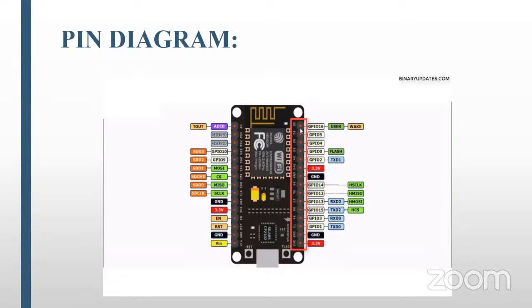Via SPI communication only, we externally read the data from the MCP3008 IC. If you are using only one analog sensor in ESP8266, no problem. But if you use two or more analog sensors in the ESP8266 microcontroller, we definitely need the MCP3008 via SPI communication. Via SPI communication only, we can read the data from the MCP3008 IC.